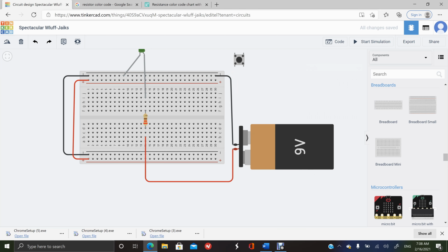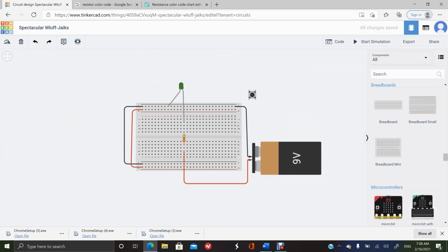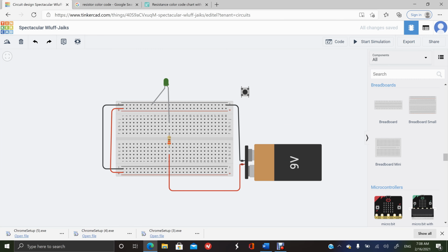Okay. Now we wanna turn this on. So with this tool, we can simulate, because we're doing a simulation. We want to see the light turn on and hopefully not burn, by clicking on Start Simulation. And you can see, it's giving a message, hey, your LED is using this value, be careful. Okay, it might not last too long. Yes, we knew that. So stop. Okay, let's now look at if we're gonna get that message again. If we go and select this, like 470 ohm. Okay, and notice the color has changed. Okay, now let's start simulation. Oh, we don't have any issue now.